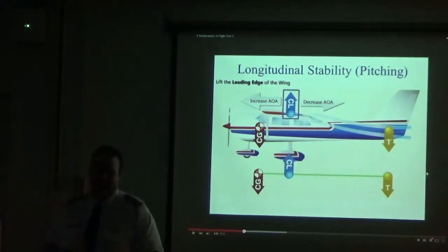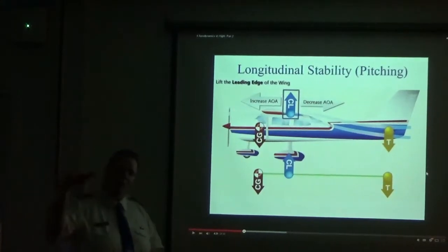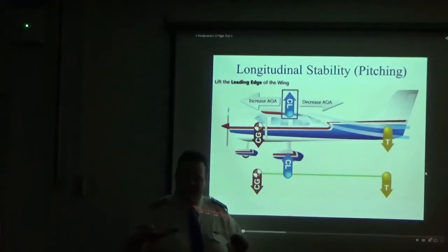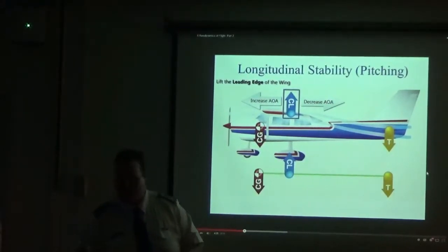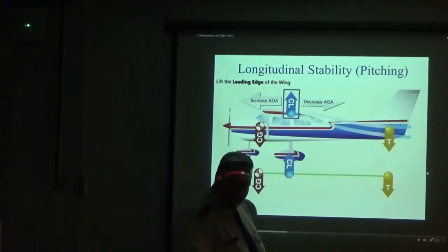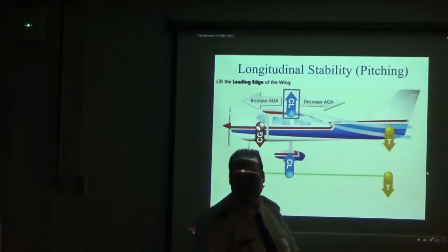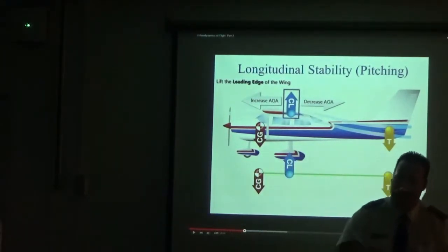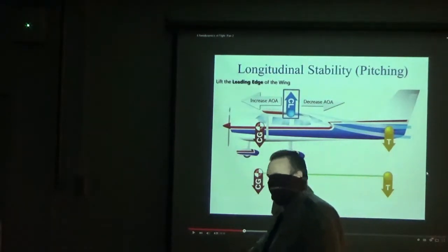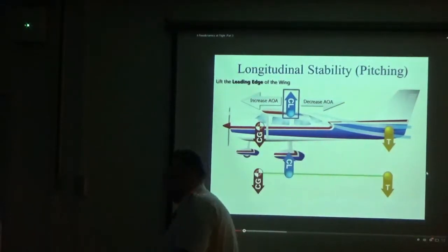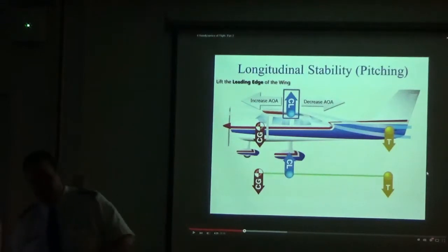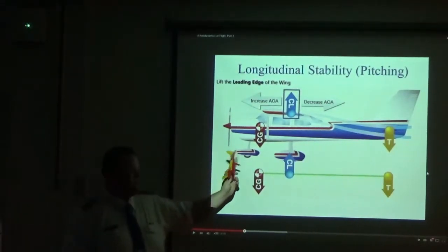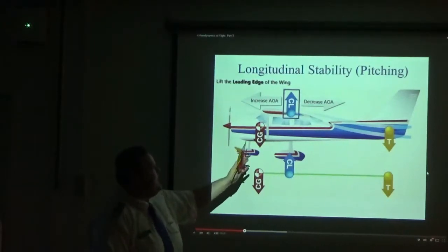So they're coming down on final, and they're still way outside of the weight limit. Their center of gravity is okay, I believe, but their weight was still over. And as they touched down, the landing gear collapsed. It just snapped out from under it, and they belly flopped on the ground. Completely totaled the plane. So center of gravity is very important. Weight is almost just as important, just for the structural stability of the aircraft.